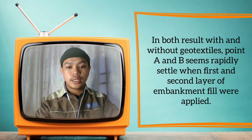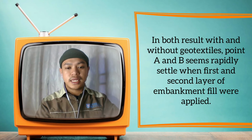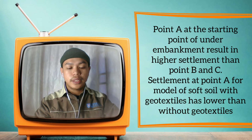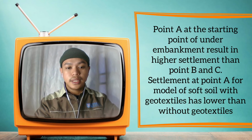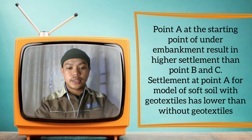For the result with and without geotextiles, points A and B show rapid settlement when the first and second layers of the embankment fill were applied. For point A at the starting point under the embankment, the result is higher settlement than points B and C. Settlement at point A for the model of soft soil with geotextile is lower than without geotextile.